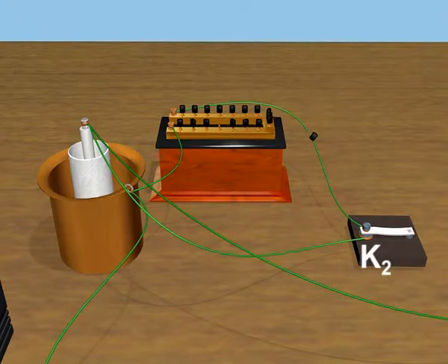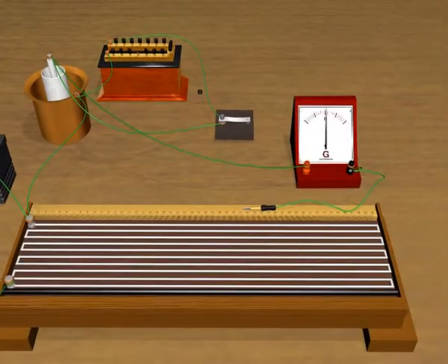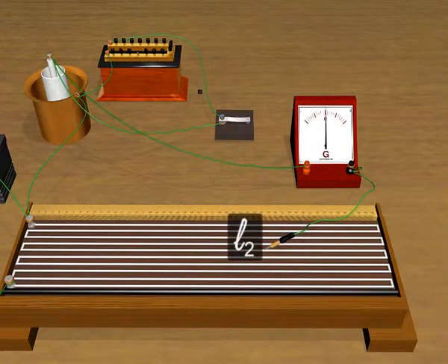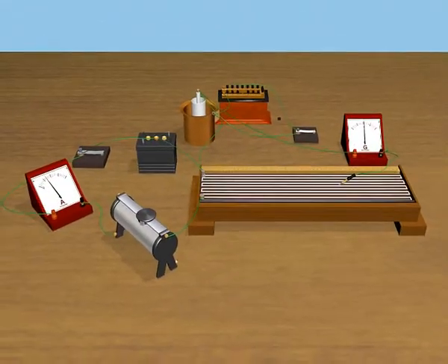Adjustment is made from the resistance box connected in parallel with the cell. The jockey is gently slid over the potentiometer wire till a point where the galvanometer shows no deflection is obtained. The null point position is accurately obtained and the balancing length L2 is noted. Knowing L1 and L2, the value of the internal resistance of the given primary cell can be measured.